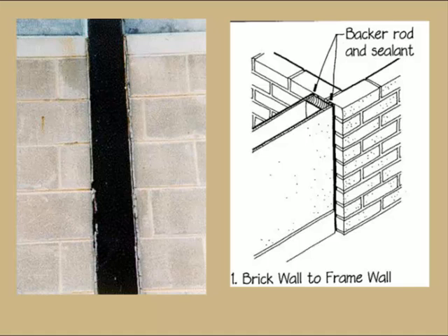Good. Now looking at something very critical, Russ, in this next building wall subsystem or building wall component would be flashings, looking at through-wall counter flashings and weeps, sill and head flashings at the wall openings.